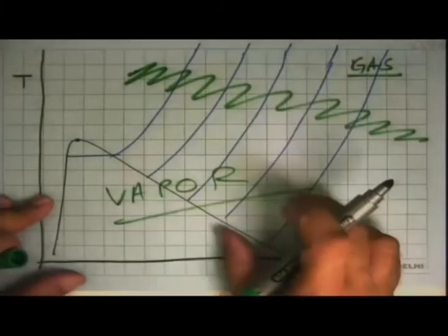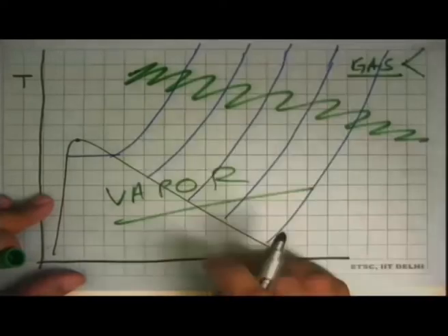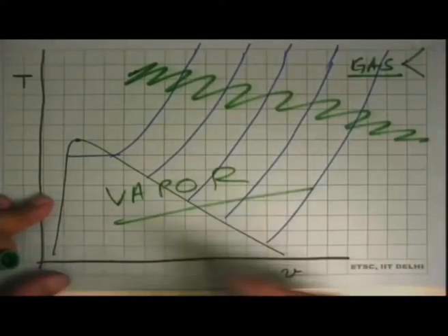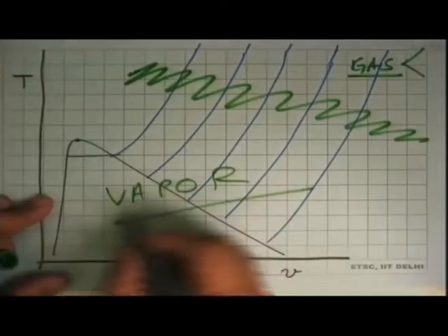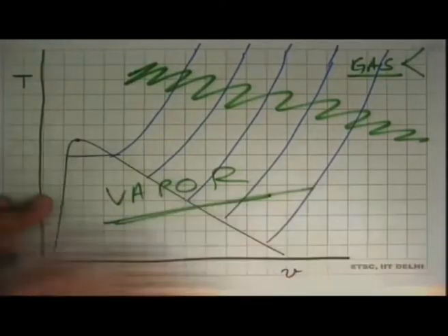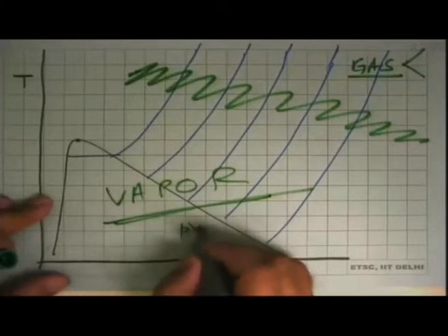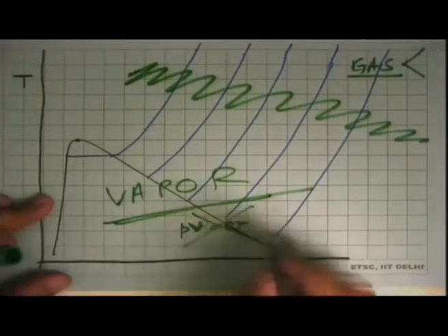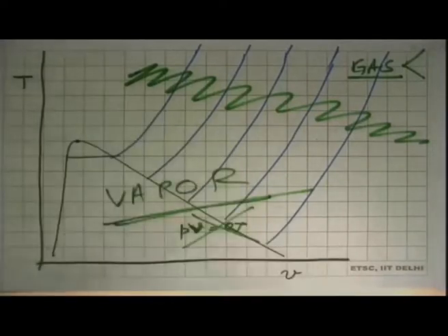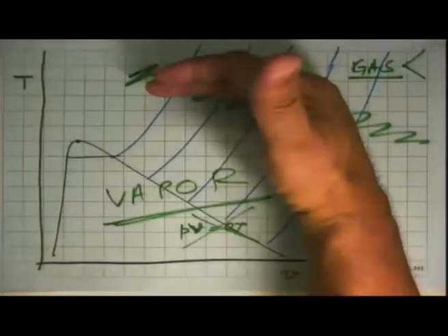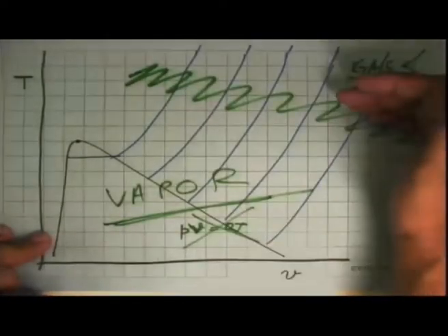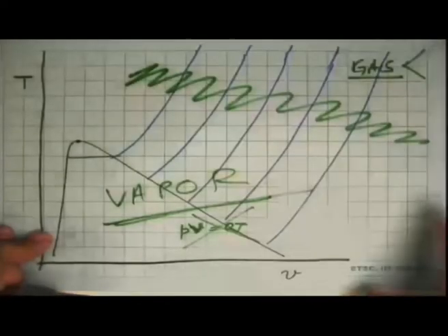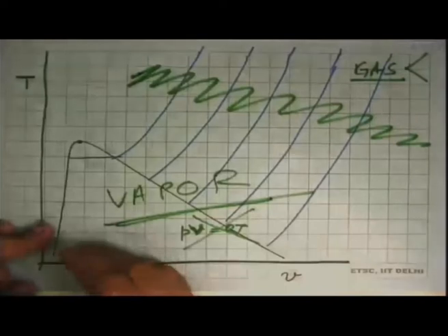And these are the two very distinct regimes. And within this gas we will now see ideal gas and real gas. But the fact is that in this condition where there is a vapor-like behavior, we should not even think of PV equal to RT. Completely wrong. And that's why all property diagrams end at some point, and they do not give the chart properties beyond that, because then it is presumed that after this range of pressures and temperatures, the substance behaves like an ideal gas. You can start using ideal gas equations of state, and you can forget about this part.